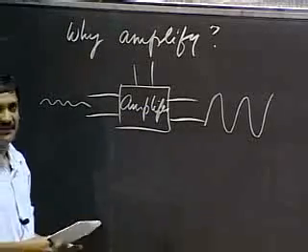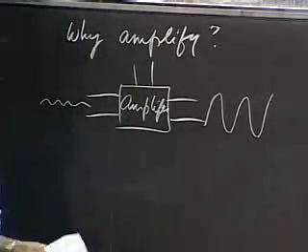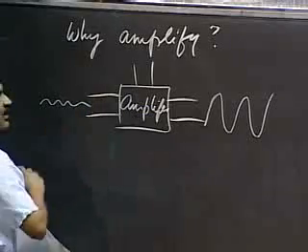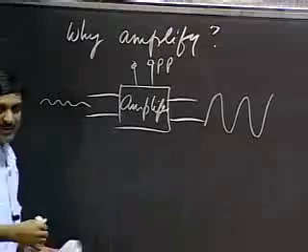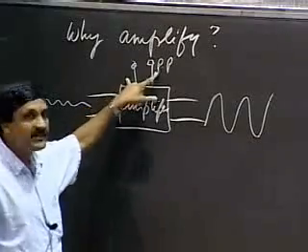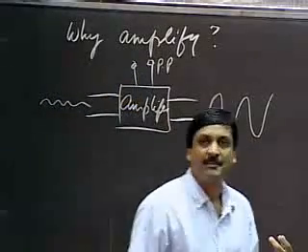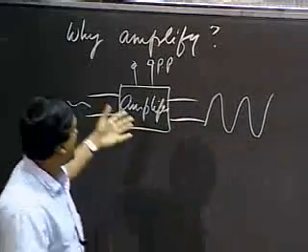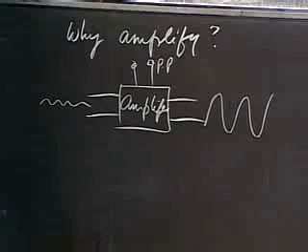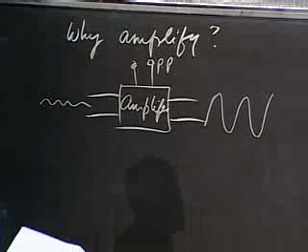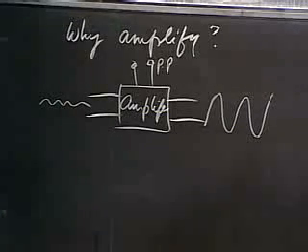And commonly, the amplifier, in addition to an input and an output, input port and an output port, may also contain a power port, okay? So that I can apply a power supply to the amplifier because commonly, as an amplifier signal, I'm looking for a power gain as well, an increase in the power provided by the output.